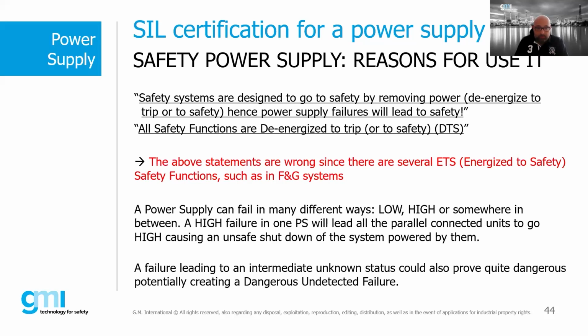There are two types of dangerous fault condition that we need to address. The first one is an undefined load voltage in a range between 2 and 20 volts, usually called an undervoltage condition, which must be considered a dangerous failure. This is because an incorrect power supply to the load can lead to a reduction of the performance of the load and can cause a premature instrument failure. This problem can be overcome using a redundancy configuration, but it is not always sufficient with the standard device and does not make us immune from possible faults from the power supply itself.